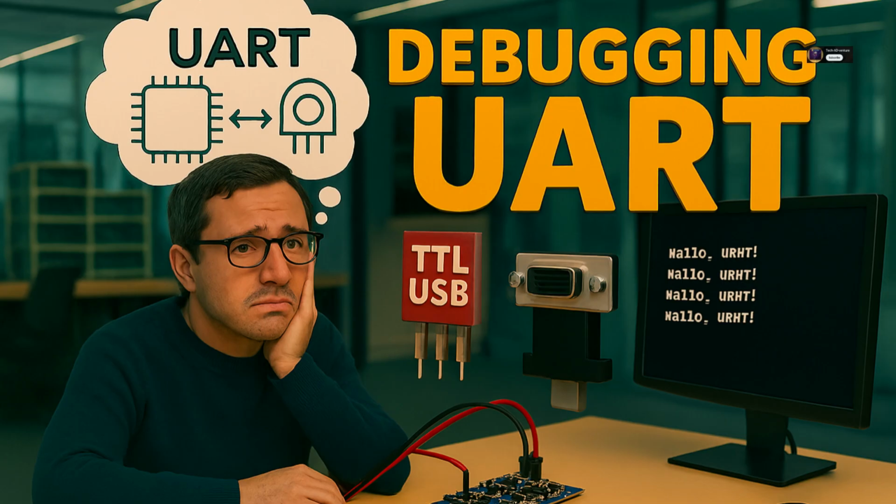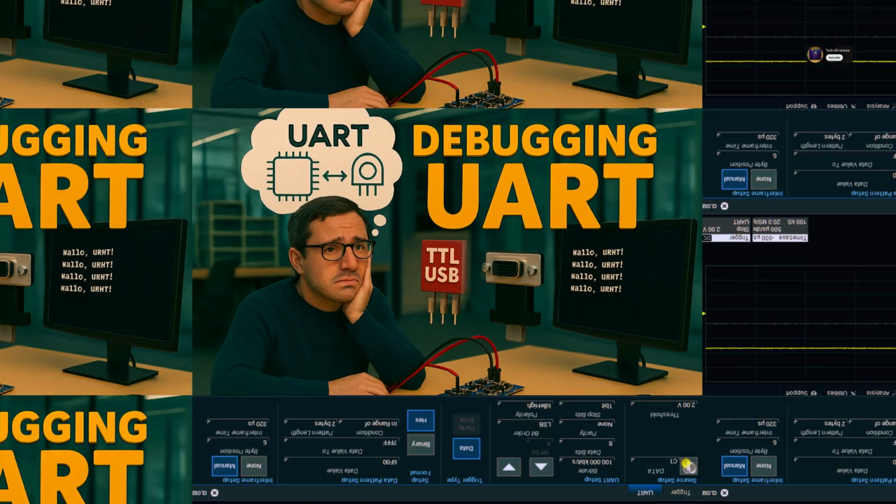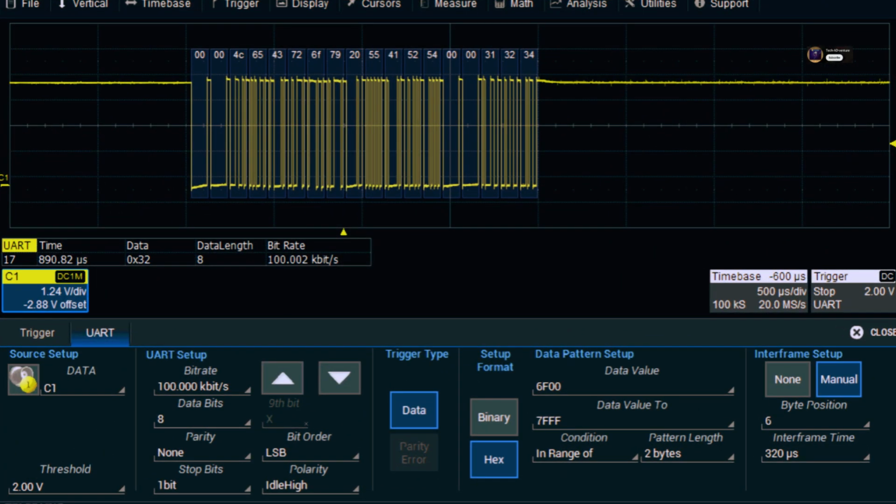Okay, let's talk troubleshooting. Things inevitably go wrong sometimes. What are the essential tools for debugging UART issues? Oh yes, debugging UART can sometimes feel like black magic if you don't have the right tools. The number one most helpful tool is probably a logic analyzer. This device captures the actual digital signals on the TX and RX lines over time. It lets you see the bits, the start and stop bits, the timing.